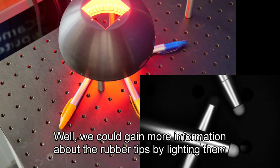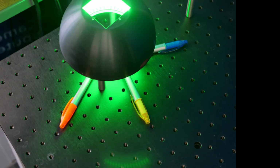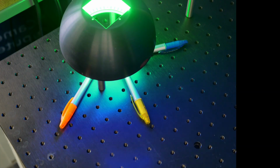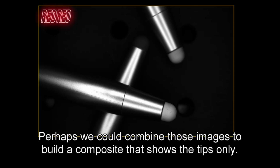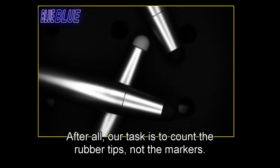Well, we could gain more information about the rubber tips by lighting them with different wavelengths of light. That information would help us differentiate tips from the marker body. Say, capture an image with red light, an image with green light, and an image with blue light. Perhaps we could combine those images to build a composite that shows the tips only. After all, our task is to count the rubber tips, not the markers.